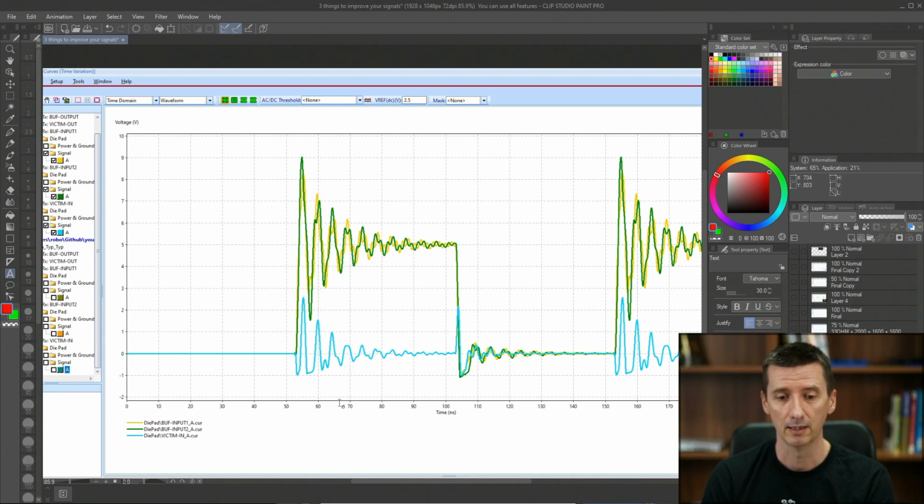Even if this signal is slower than 10 MHz, you still can have this kind of noise, because, as you could see, what is important is the rising and falling edge, how fast the buffer you are using in your circuit is, because the type of this buffer will specify the rising and falling edge of the signal. So even for slower signals, you still can have this kind of high noise in your boards.